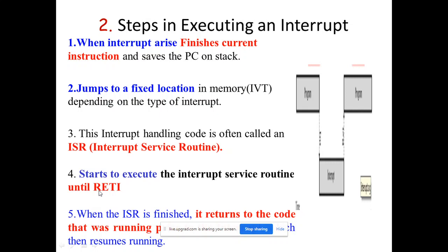until the RETI, return from interrupt, instruction is reached. All instructions are executed one by one continuously, and at last the RETI instruction comes. RETI is nothing but return from the interrupt service routine, and at that time the address of the main program is popped from the stack and the main program starts again. Here the controller is initially executing the main program, and in between an interrupt arises. At that time the controller stops, and the PC is held on a stack with the help of which instruction?